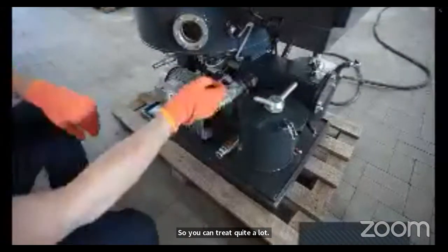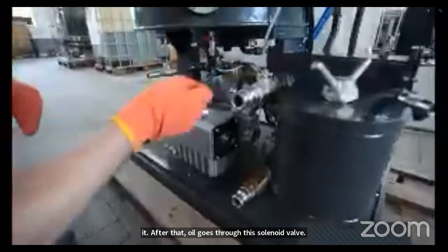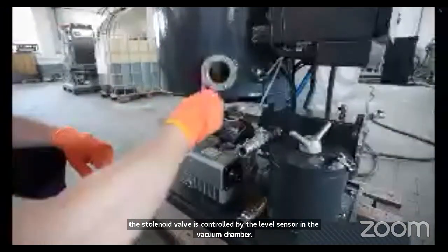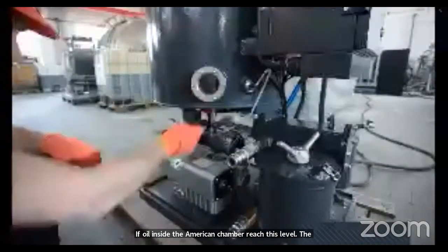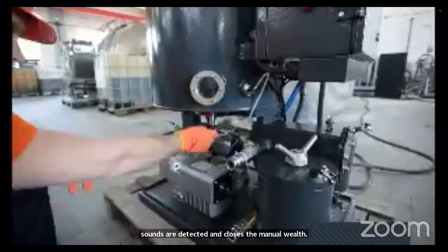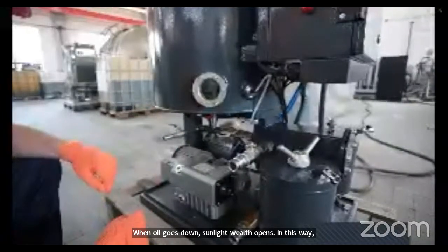After that, oil goes through the solenoid valve. The solenoid valve is controlled by the level sensor in the vacuum chamber. If oil inside the vacuum chamber reaches this level, the sensor detects it and closes the valve. When oil goes down, the solenoid valve opens. In this way, a certain level is maintained in the vacuum chamber.